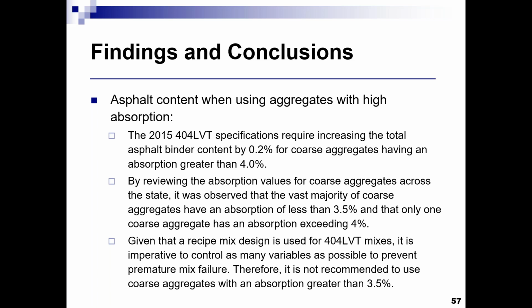We did look at basically in the specification, it says add 0.2 percentage points of asphalt binder content if you're using high absorptive aggregates. And there is only one aggregate with more than 4% absorption in the state.